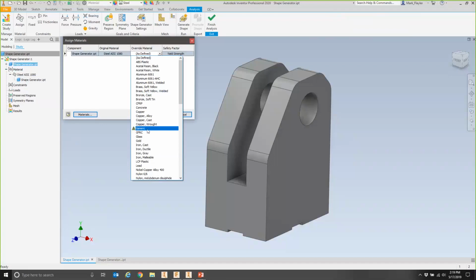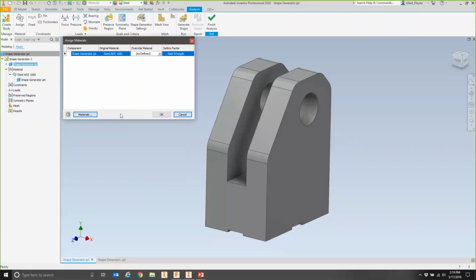Of course, you don't want to make everything out of generic. That's your default material. I can't wait to go to the store every day and pick up a new box of generic. So obviously certain things don't work for that. Wood and water are also outside of the criteria here, and so is rubber. Usually the Poisson's ratio throws this off, and that's why you can't use it as a material.